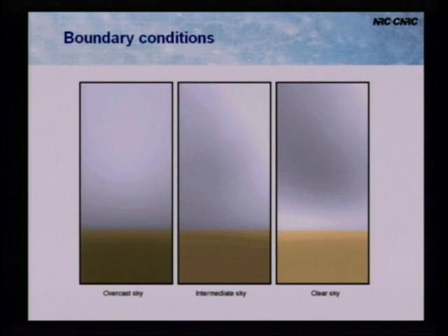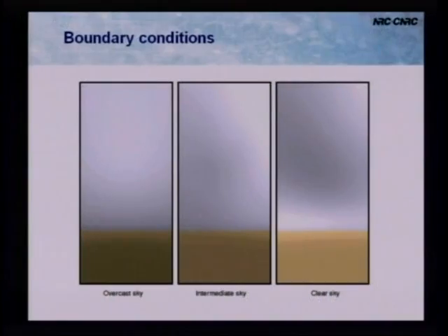When you've defined what you want to look at and how you're going to model it, you also need to look at what conditions you are going to analyze its performance in. So on the daylighting side, daylight factors, the standard measure of daylighting within a building, are defined for an overcast sky, but we know that the sky is not always overcast. So you possibly want to look at your model with the overcast sky, but maybe some other sky types. And if it's a clear sky with the sun in it, what time of year do you look at? Do you look at the winter solstice, summer solstice, spring? When do you look at that model?